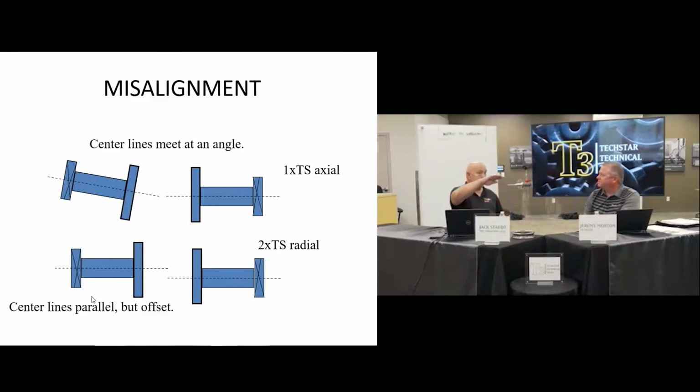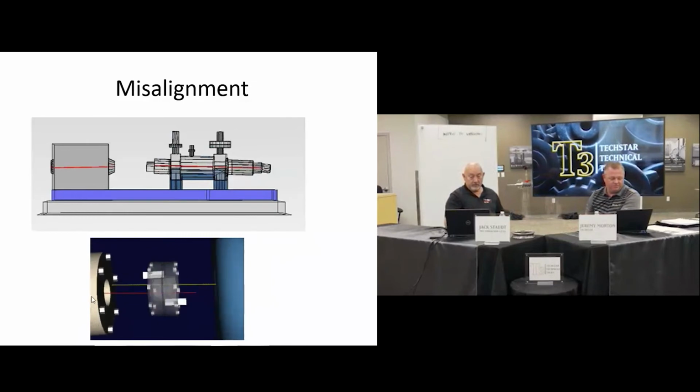If you looked at the trend, it was just trending up, and it finally went into alarm. So was that axial vibration or axial position? It was axial position, which was giving a deflection of the coupling. The other story on this is that the RPM was at 8,200. Oh, wow. So the higher the speed, the more sensitive the alignment is. Makes perfect sense. Interesting.